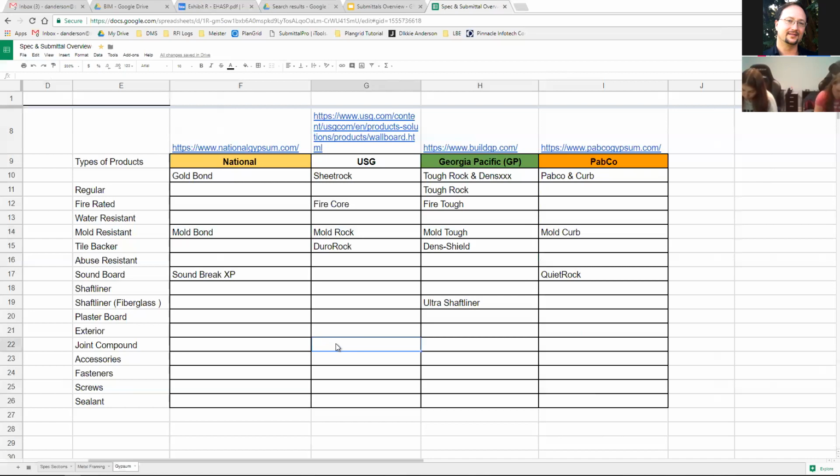So based upon what I just shared, what do we think hot mud is? It dries quickly. That's right. Hot mud has a chemical additive in it that allows it to dry very quickly. So if you want it to dry in 90 minutes, you use 90-minute hot mud. If you want it to dry in 60 minutes, you use 60-minute hot mud, so on and so forth. 10-minute hot mud is full of a bunch of chemicals that react to have it dry very quickly.